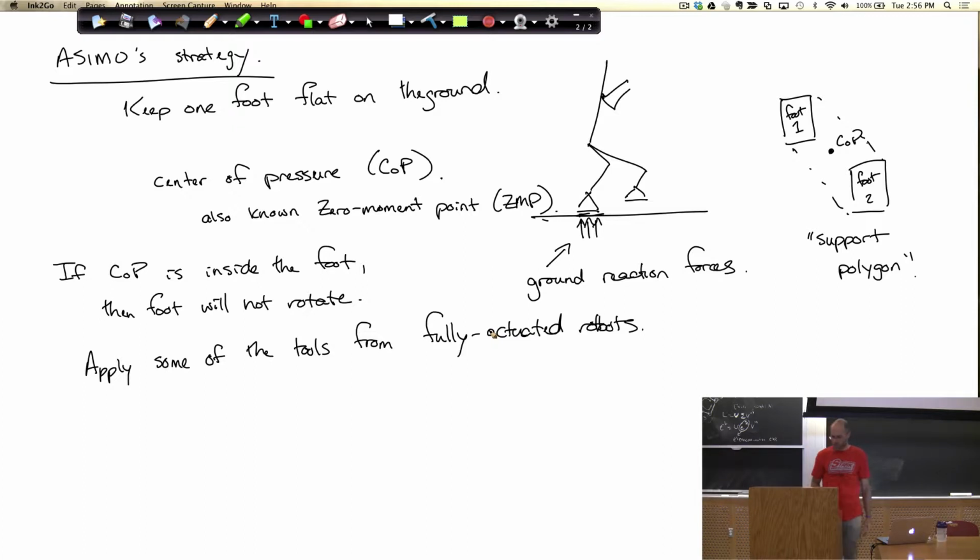things, right? So a lot of the initial work on humanoids would, for instance, follow almost arbitrary trajectories. You would motion capture someone doing an exotic dance, put it through a sort of filter, which makes sure that none of the accelerations during this motion are going to move my center of pressure to the edge of the support polygon.